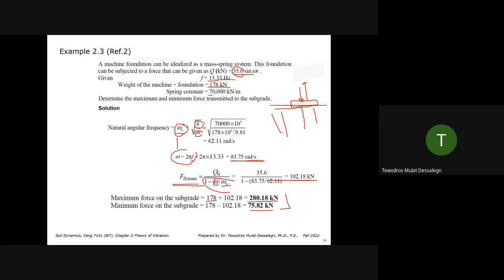So this is probably a new concept for most of you, what resonance is. But resonance, in simple terms, with these simple examples with 1 degree of freedom, that's what it means. But it happens the same way with complex systems. When you model your structure, a thousands of degrees of freedom system, you'll have different modes of vibration.